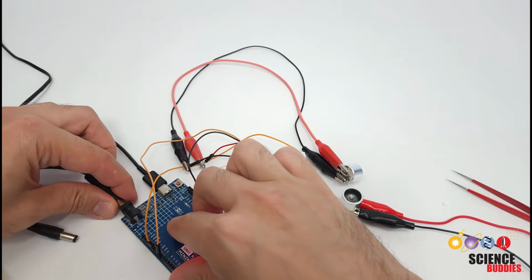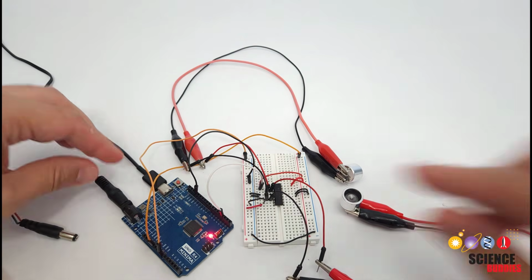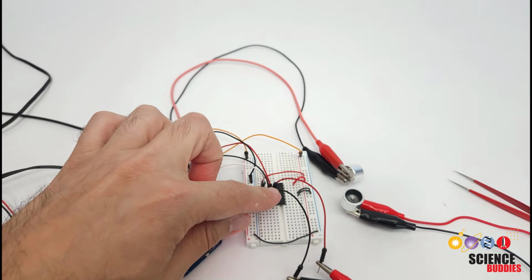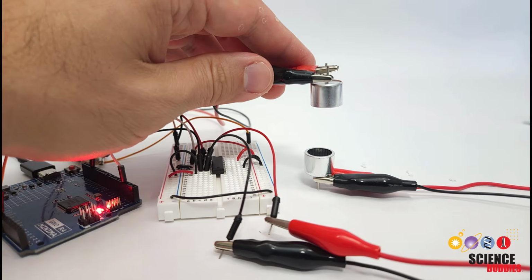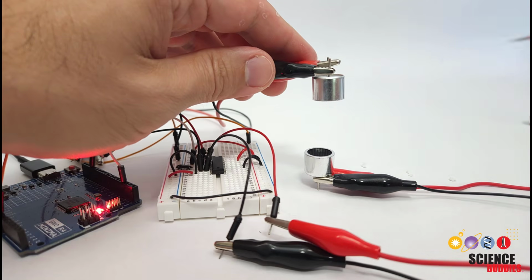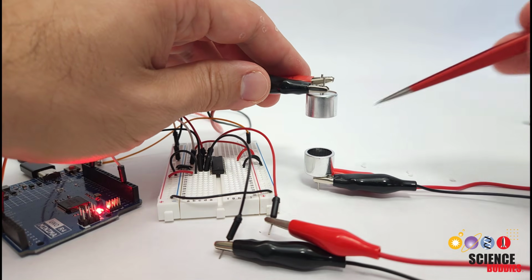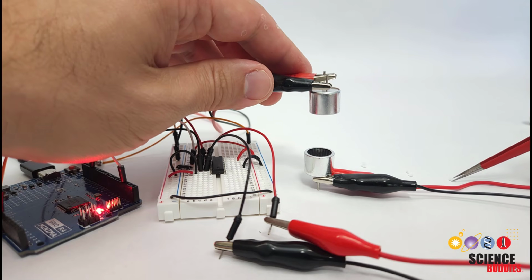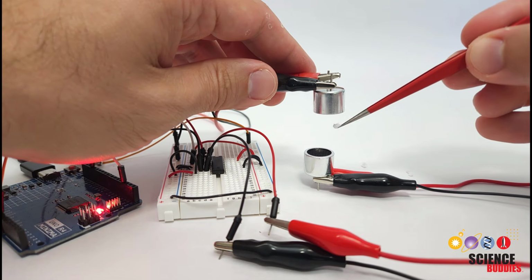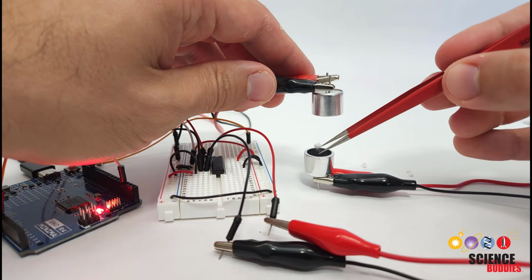So again, I'm going to plug that into the Arduino. My jumper wire is still in place, so the H-bridge is now being powered by 12 volts. Let's see if it works. So here we go again. I have my H-bridge, which is now being powered by 12 volts. I have my transmitters. I'm going to hold one above the other and very lightly grab a little piece of foam with these tweezers and see if I can get it to hover.